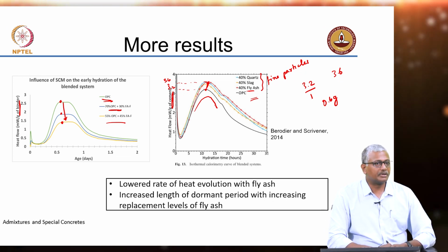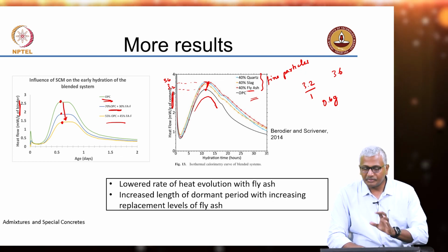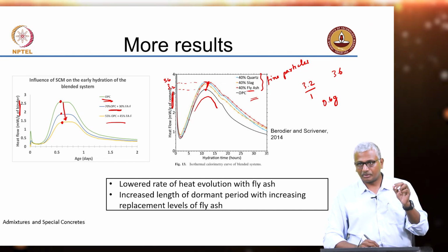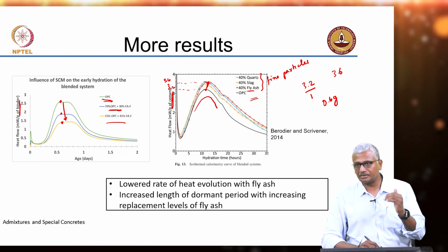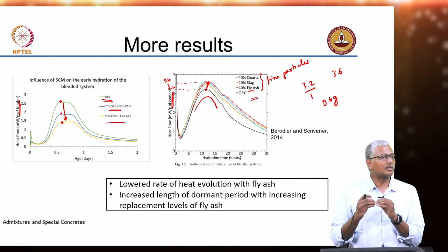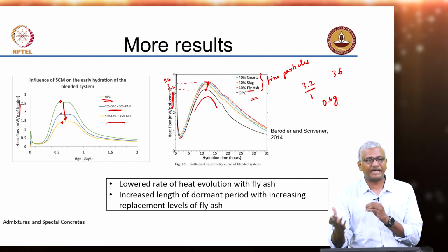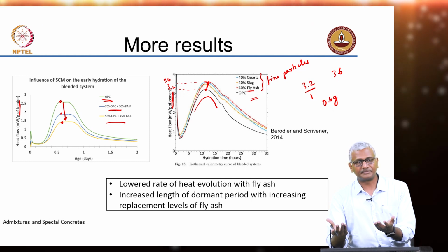Okay. So, you should also look at how the result is represented, but this also signifies that every cement grain that is present or every C3S that is present, the hydration of that phase has been accelerated. So, you are getting from the available cement a slightly greater amount of heat, because fly ash at that early age is not going to contribute any reactivity.